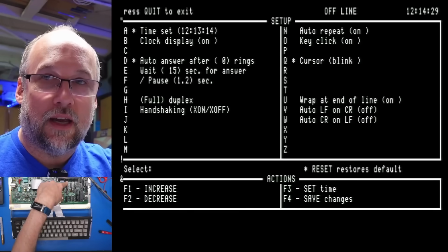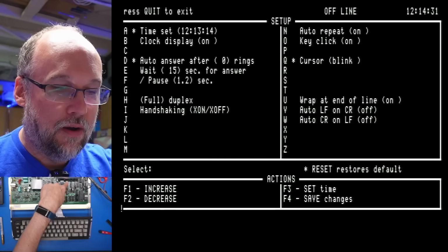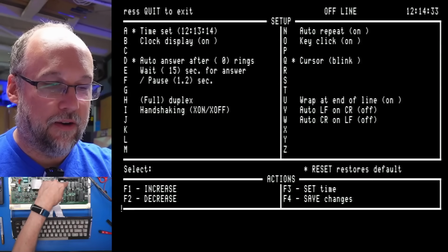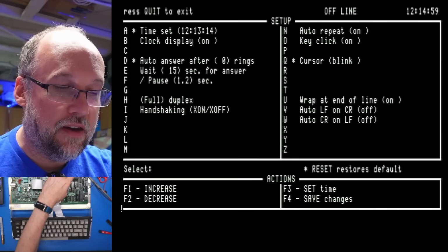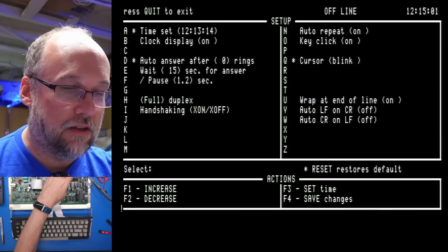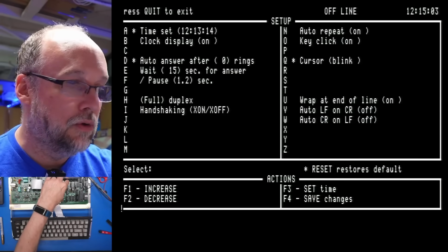So I think it was designed with this SRAM chip powered all the time when the system is running. It's not using the battery power. And when the system gets powered off, then it's using the battery to keep the contents of the little SRAM chip alive. I'm going to remove that SRAM chip. Let's just see if that has any effect. All right, there it is, the little NEC SRAM chip. Let's see if this thing can operate without it. Who knows what it will actually do.